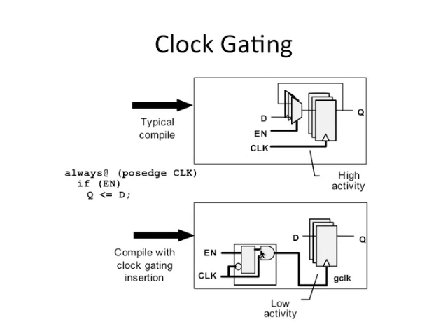So the enable input of the clock gate is essentially latched out here, and you see the negative edge of the clock is used to latch the enable input. When I use a negative edge, the change of the output happens only just immediately after the negative edge.